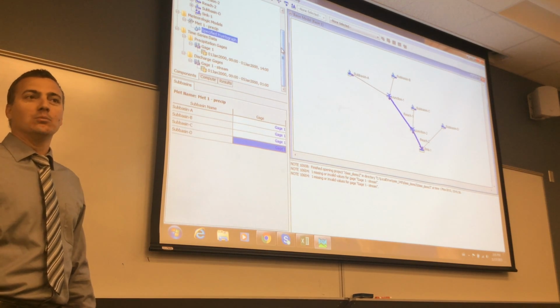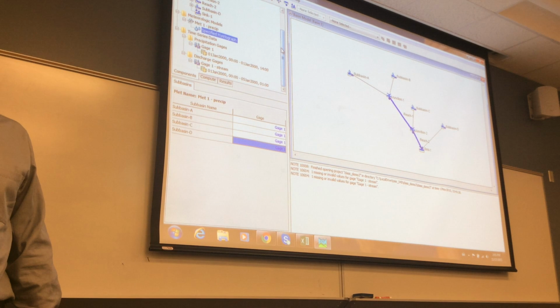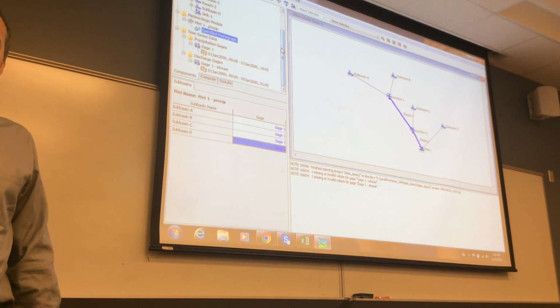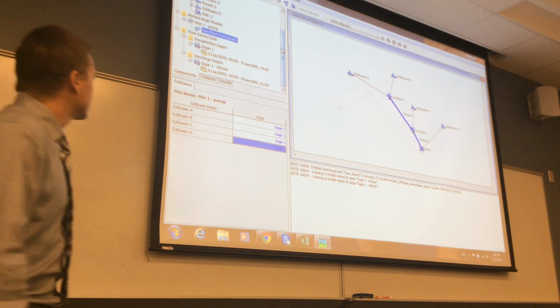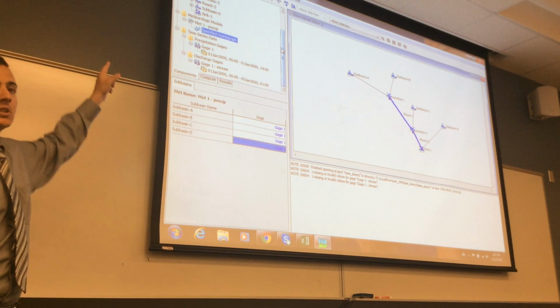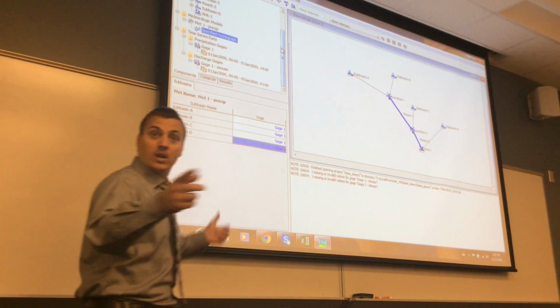So in the case that you have, let's say 2 gauges assigned to sub-basin B, would the program give you the option of adding 2 gauges? Yes. Or, well, you could have chosen to use a Thiessen, for example. Or you can even use gridded precipitation, as you had.